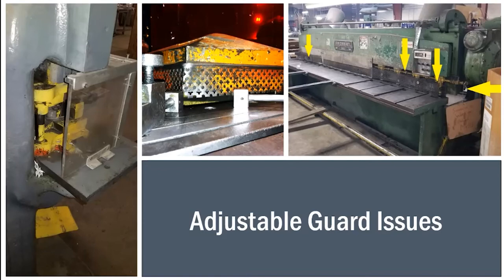And, you know, guards get modified, taken off. This press brake, the OEM guard, was removed and put on this fabricated guard here. You know, on the left side, it's probably not too bad. On the right side, this extruded metal mesh isn't necessarily as adjustable. So there's a gap at the bottom where you can reach into the dogs, which is that crush hazard, or you can reach over it to the shear in the back, which is the cutting hazard.